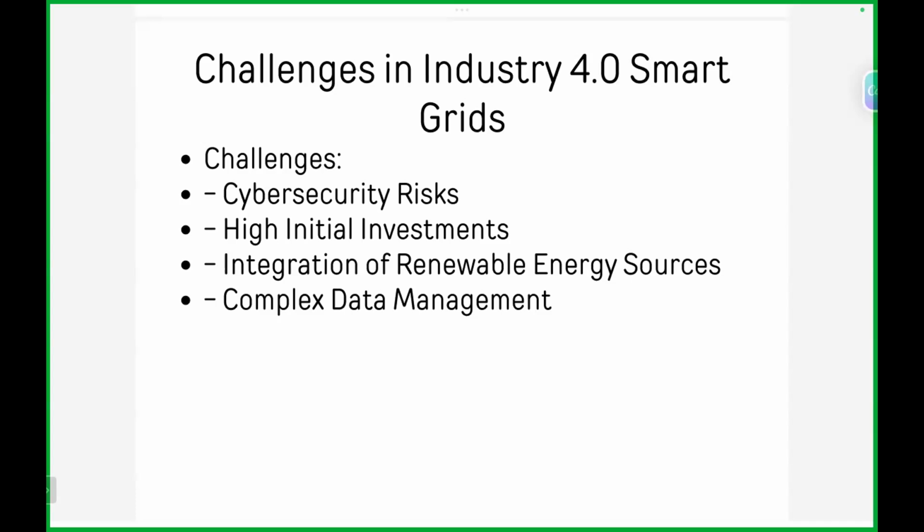So for that, the government is now taking an initiative on DSM, the Deviation Settlement Mechanism, where 24 hours are divided into slots. Each hour is divided into four slots of 15 minutes. In total, you will have 96 slots to control generation as well as consumption. So this will help grid integration in a smarter way.